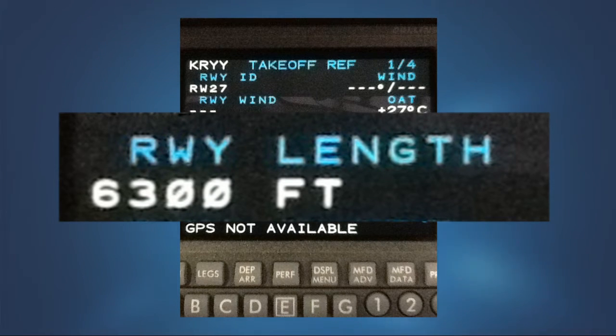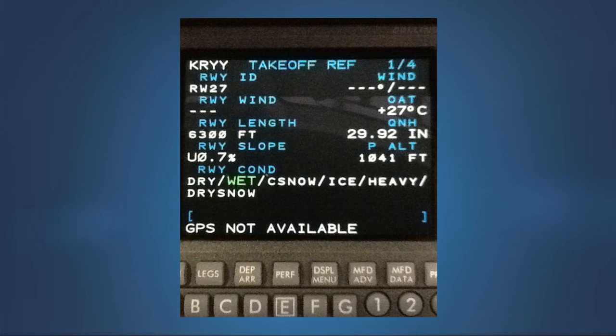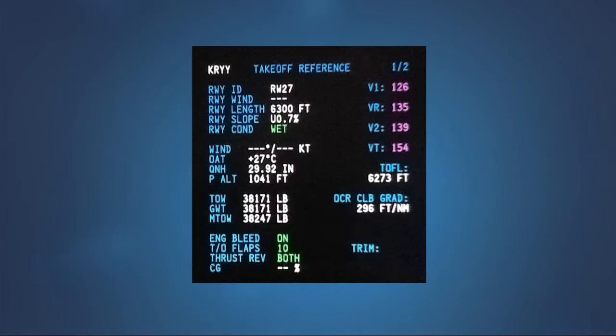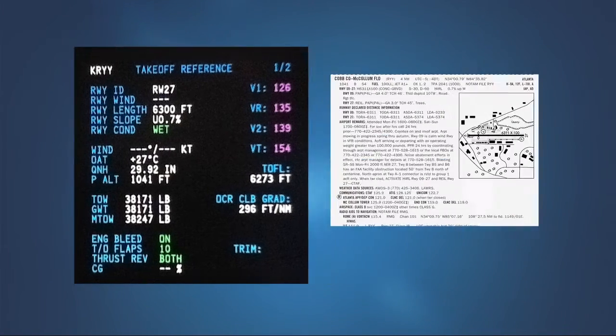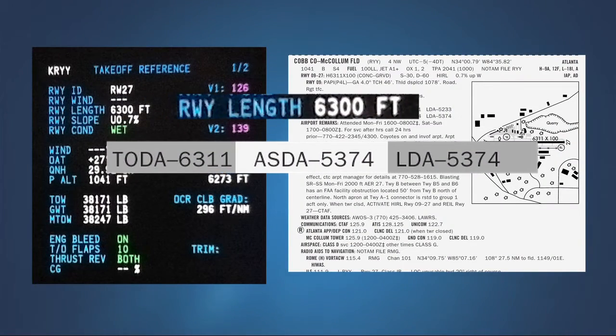The runway length stored in the navigation database may not reflect a runway's declared distances, or the length of a runway remaining beyond a displaced threshold available for landing. For those flight management systems that do provide takeoff and landing performance calculations, the results of these calculations may not reflect the true maximum allowable takeoff and landing weight for that runway based on conditions.